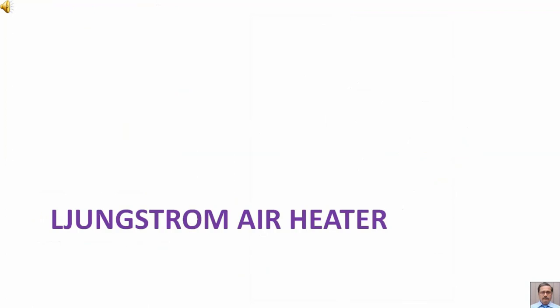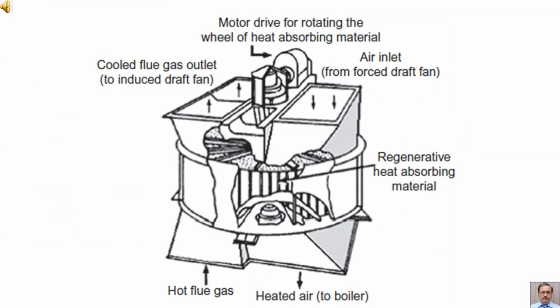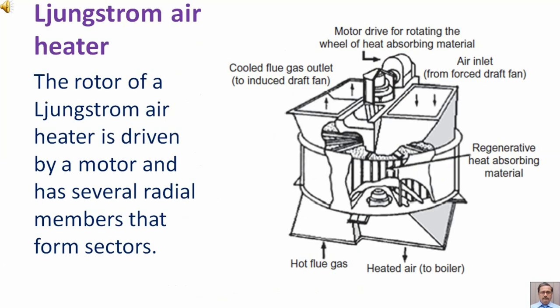Ljungstrom air heater. The diagram of Ljungstrom heater is shown. The rotor of Ljungstrom air heater is driven by a motor and has several radial members that form sectors.